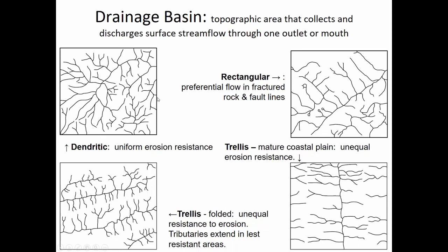And one of the things that's really extreme in West Virginia is we'll see watershed slopes that are routinely in excess of 40%, where outside of West Virginia, I don't know of any other state that has such consistently high watershed slopes. And so although we have these dendritic patterns, which you think maybe that's going to slow down the movement of water, what speeds things up and makes things so flashy here in the state is the fact that we have really steep watershed slopes.